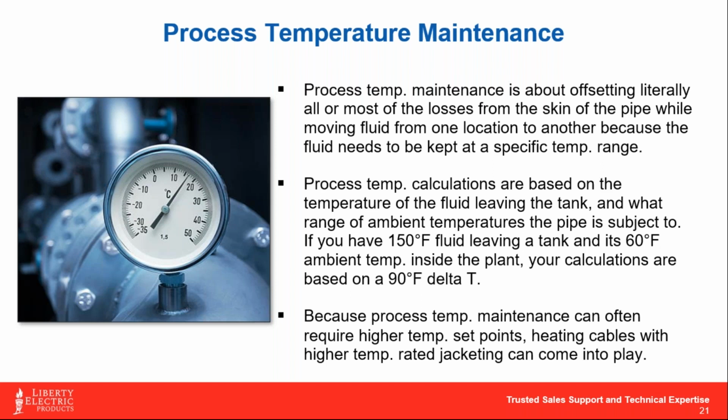So, again, just a simple example that we did in the text of this slide, if you had 150-degree fluid leaving a tank and it's 60-degree ambient temperature inside of your plant, you're now basing this off a 90-degree delta T, okay?